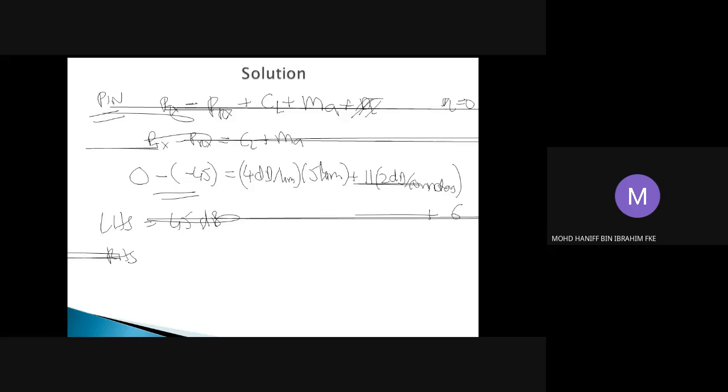For the right-hand side, the summation will be 4 times 5, which is 20 dB, plus 22 dB plus 6 dB. So we end up with 42 plus 6, which is 48. The right-hand side value is 48 dB, but the difference between the transmit and receive power is 45 dB.